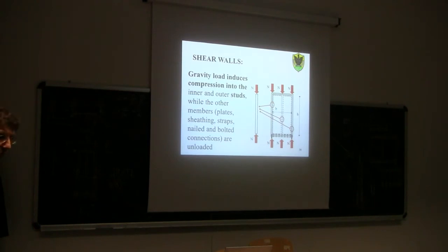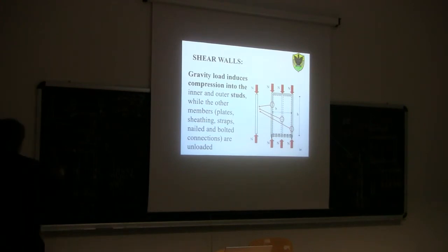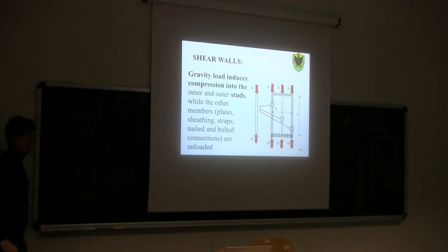So what do we need to do? We need to use this metal hold-down strap. So we need to have a metal bar nailed on the stud, which can then transfer the tensile force down to the foundation underneath.